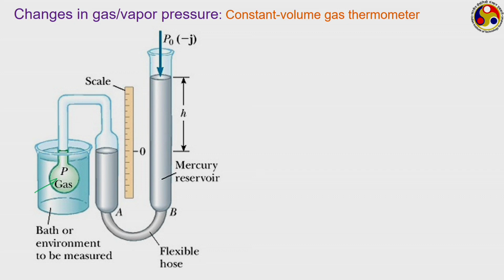As the volume remains constant, its pressure has to increase, because if this gas follows the ideal gas equation of state, we know that we have P1 upon T1 is equal to P2 upon T2 during a constant volume process. So, temperature will keep on increasing linearly with the pressure, or conversely, as the temperature increases, pressure will keep on increasing linearly with the temperature.